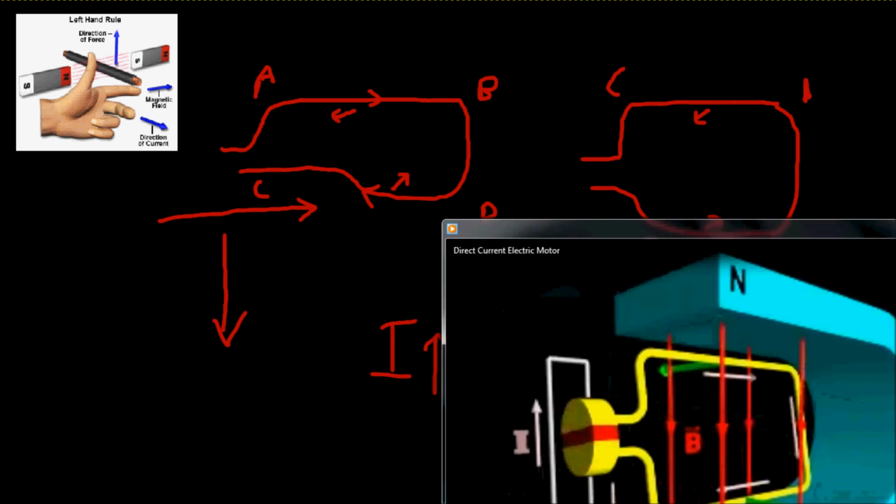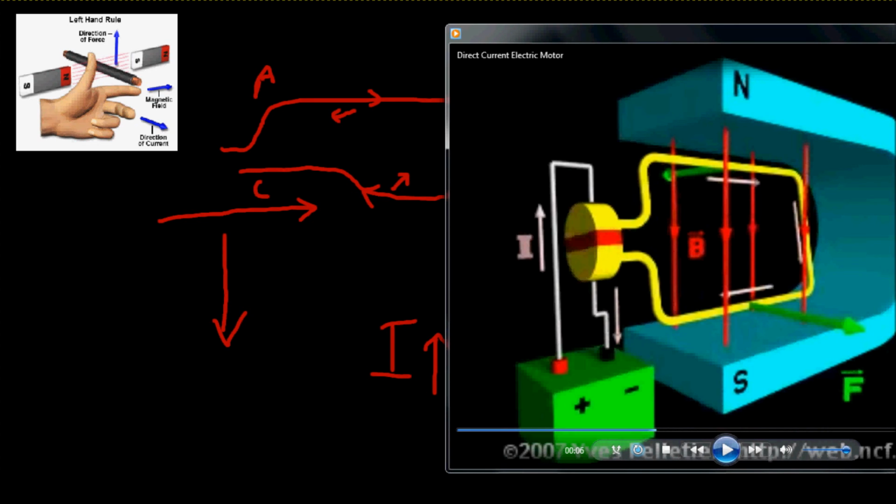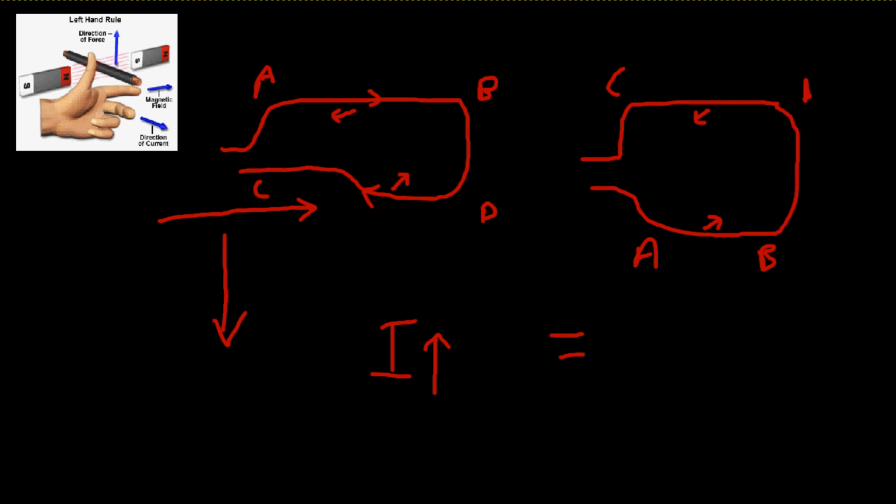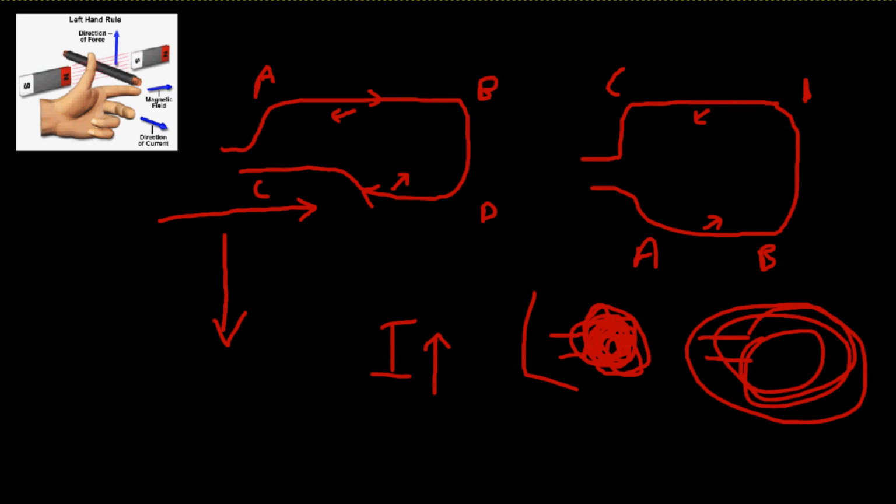But you get these 3-volt toy motors in the market. If you actually open one of those up, you'll see thousands of, not literally thousands, but loads of coils. It'll be like this. It's just a huge mess over there. You can't see it very distinctly, but that increases the speed. Another thing is increasing the area of the coil. Say you have this over here, and you have this over here. That's a bit too messy, but you get the point that if the area covered by the coil is more, the speed will again increase.